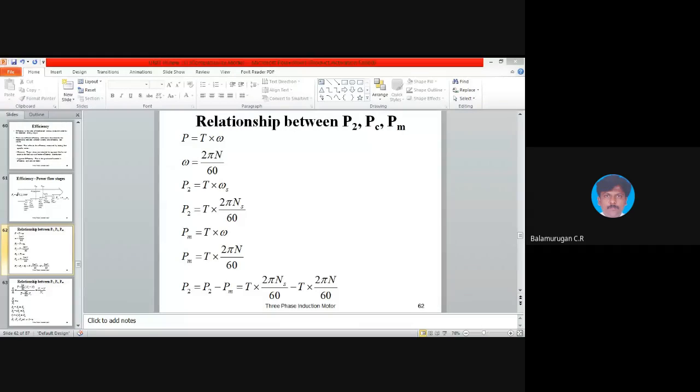State the conditions for parallel operation of transformer. Many of you referred to the net and copied the answer from the net. We know that, because if you write on your own you will write in points. Many of you wrote a paragraph. If you type in the net you will get some answer, and you simply copied it. You have to write in points: same phase sequence, same voltage, same frequency, same impedance. You should not write in a paragraph.